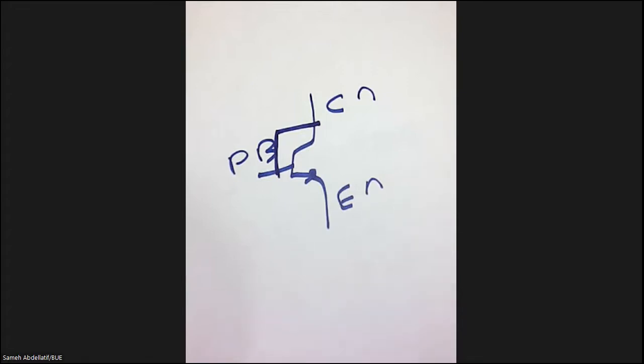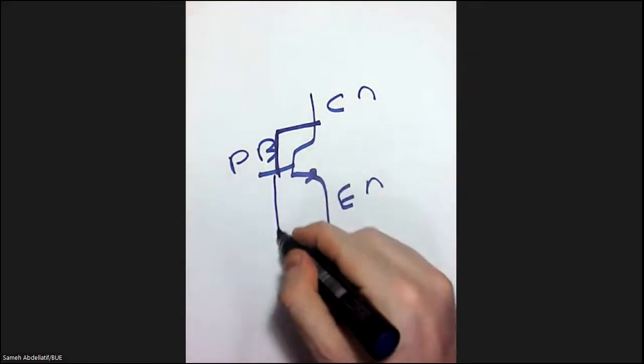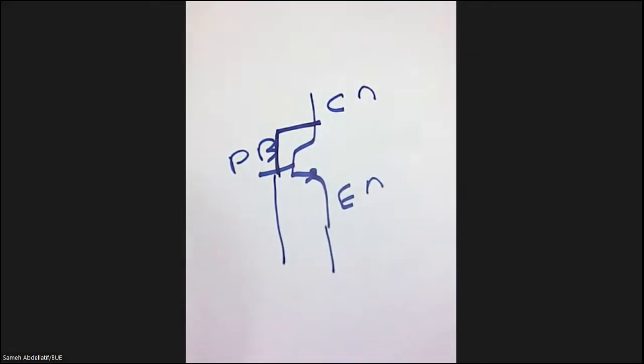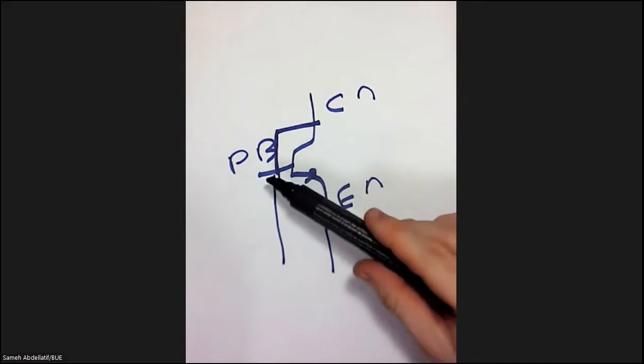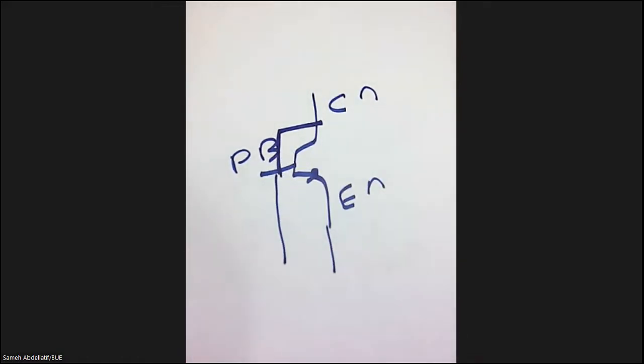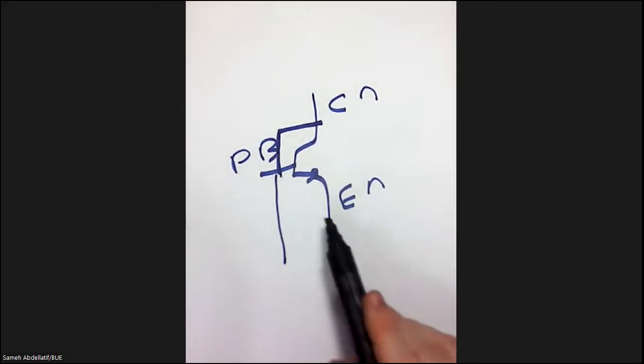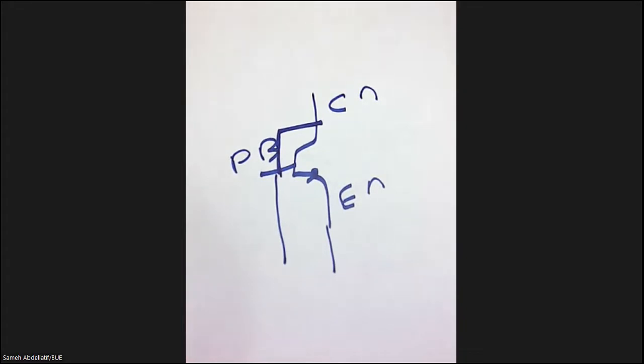So now the remaining two terminals, it's now a two-terminal device, not three-terminal, because we simply connected two of these three terminals. The remaining two terminals of this device are simply a PN junction, or a diode. And this is one of the very commonly used techniques to make a diode using transistor technology.